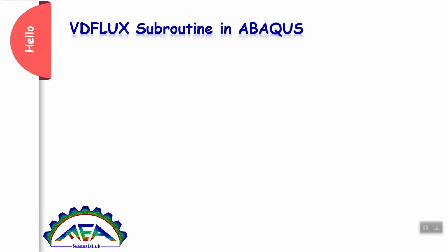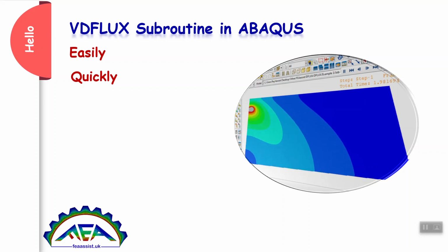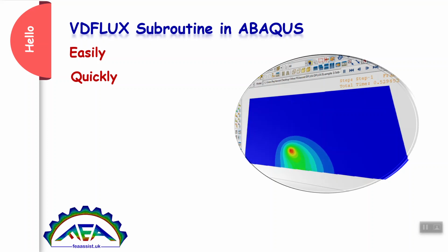Hello, you want to learn the VDFLUX subroutine in Abaqus easily and quickly. Actually, VDFLUX is a subroutine to have a movable heat source on your plate or on your sample, which is used in some processes like welding or additive manufacturing. This subroutine VDFLUX is solved by a temperature displacement explicit solver in Abaqus. To understand how it works, stay with us.